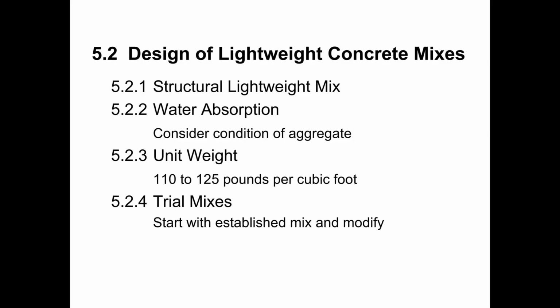Cranes are expensive, and generally the cost of the crane is directly related to the capacity of the crane. So a higher capacity crane generally costs more than a lower capacity crane. So if by using a lightweight concrete mix design, we can get away with using a lower capacity crane on the job site, then that could be a significant amount of savings in the erecting process. So that's one reason why we might want to use a lightweight concrete mix design.